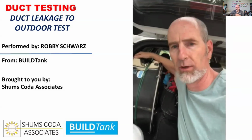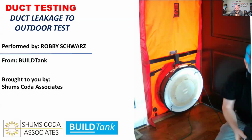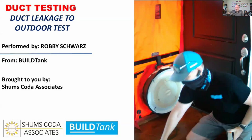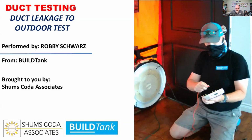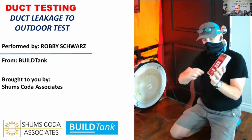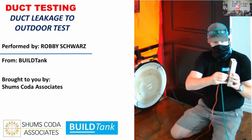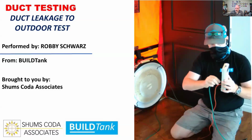Hi, in this video we're going to use a duct blaster and a blower door to measure duct leakage to outside. So just like what we did with the duct leakage test, we're measuring pressure in the house in relationship to outside the house. Before we were measuring the duct pressure inside the duct in relationship to outside the duct. So I am going to measure the house pressure, which would be the input in reference to outside. So my first goes here, and then I'm going to be measuring the fan pressure in relationship to the house.